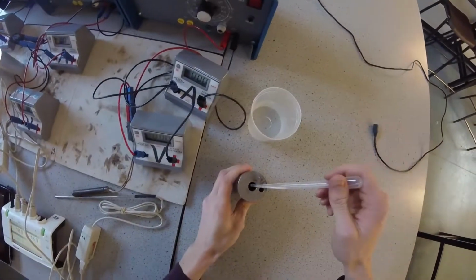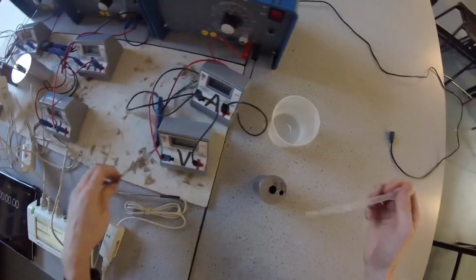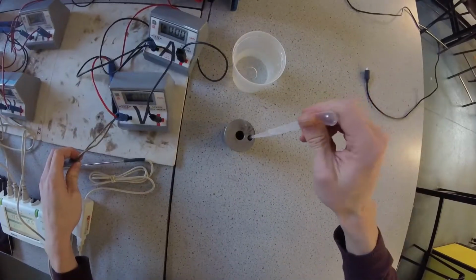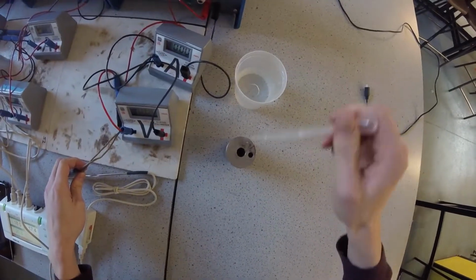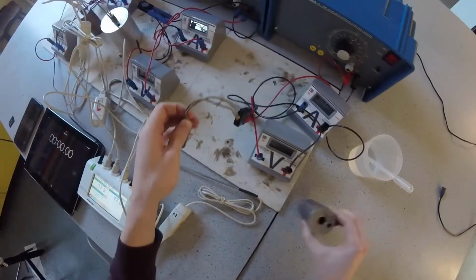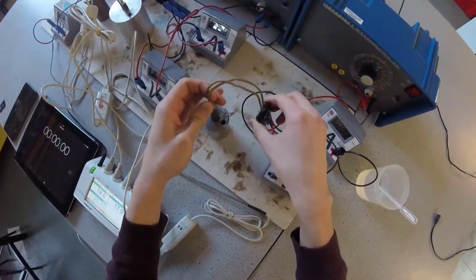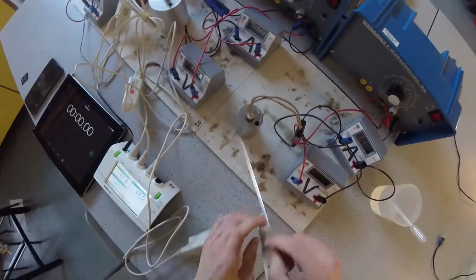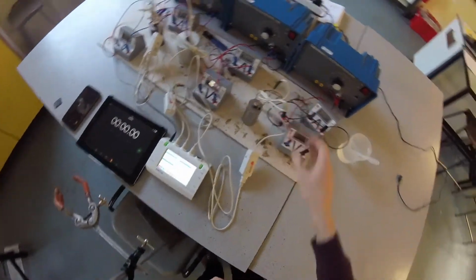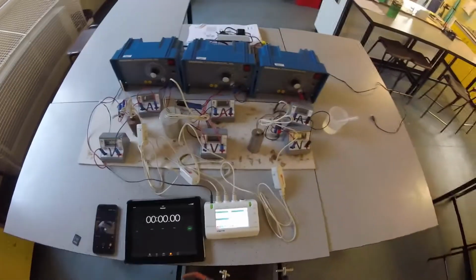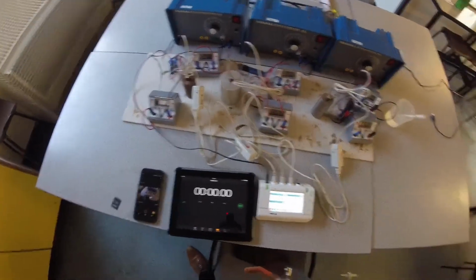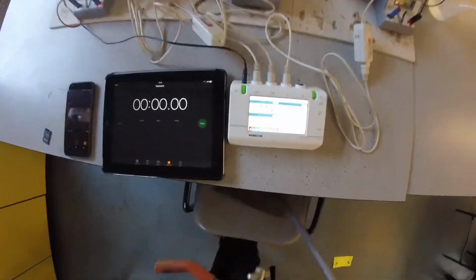Right, so it's a bit weird, look at what I'm doing. I'm putting some water in the holes. The whole reason I'm doing that is so that I can get a better thermal connection with the block. I'm going to fill the right-hand one up. That's the one for the thermometer. I'm going to fill that all the way to the top because I'm going to be using a thermometer that doesn't quite touch the sides. The water will provide a better thermal connection with the block, allow more heat to be transferred into the block more efficiently, and likewise it will allow the temperature probe to measure more effectively as well.